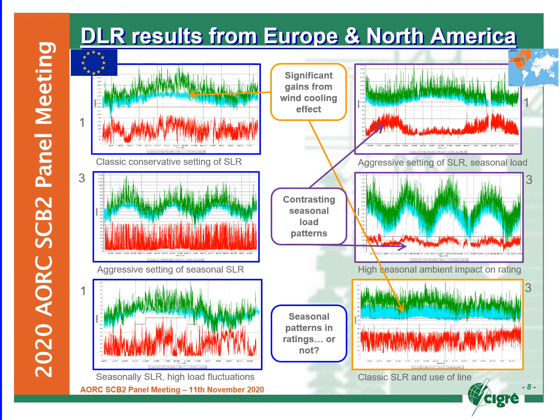This goes to show that the maximum capacity extracted by wind is really useful in cases where the line loading is high, leaving little margin between the line loading and the static line rating, and also where the ambient temperatures are generally high and stable, so the ambient adjusted rating doesn't release a lot of extra capacity.